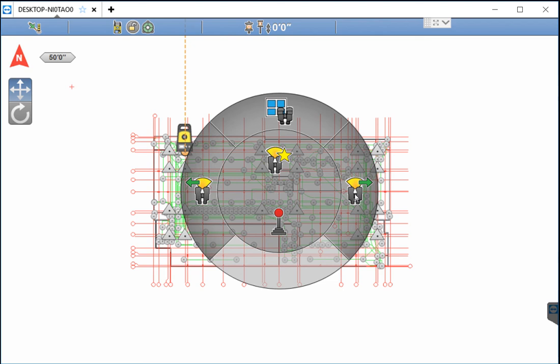you will never lock. Remotely searching and locking on the Prism depends entirely on your settings and methods. If you don't pay attention to your settings and your surroundings, you will have trouble with this. The total station can only do what you tell it to do. To continue, the button in the middle lower portion of the circle is the joystick. Let's go there.